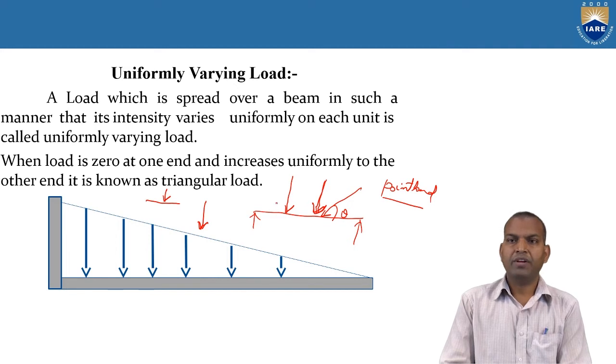So how is it acting? It is acting vertically downwards. Then what type of force does it cause on the beam? That force means the beam can either be sheared off, or the beam can also bend in the sagging direction.